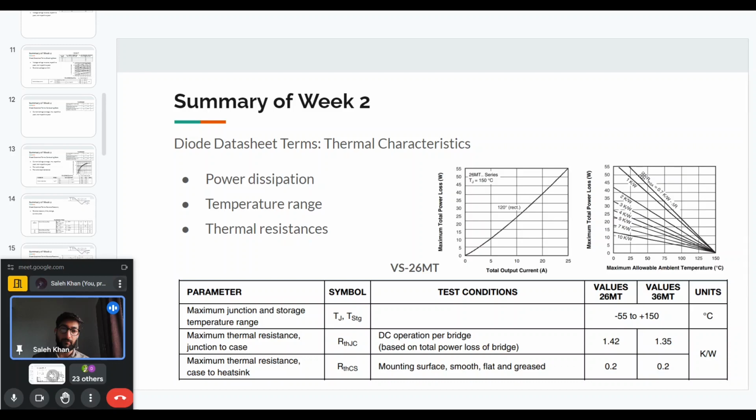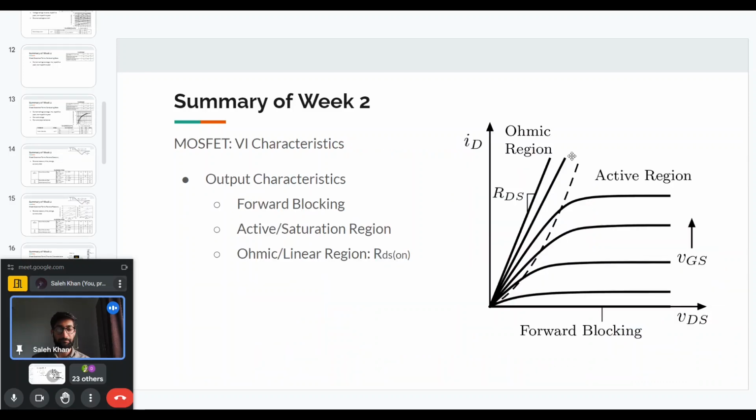So it is not an additional device that is added to the chip, just like in an IGBT, but it is inherently present in the MOSFET. You cannot remove the body diode, and that also allows a negative current in addition to the negative current that is provided by the channel. But the MOSFET can only block positive voltages.